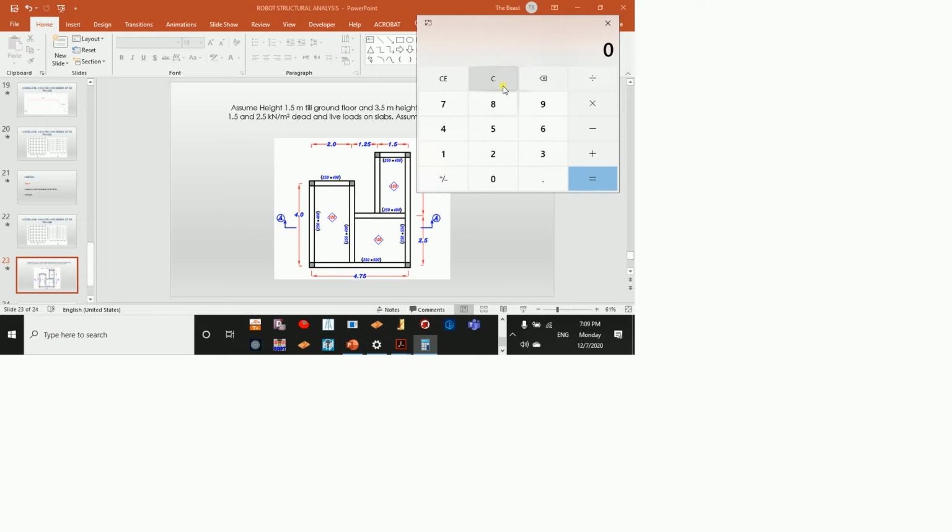We have plaster. If we are having a block, normally the block does not need plaster from all sides. There is one side, second side, third side, fourth side, fifth side, and then there are six. Now, when it comes to this block, I don't need plaster from the top or from the bottom because there are still blocks. I don't need it from this side or this side. Only I need it from the outer side. So there are two sides to be plastered. That plaster is going to be additional load on a beam.